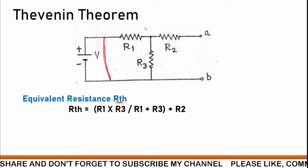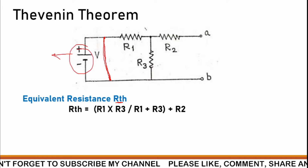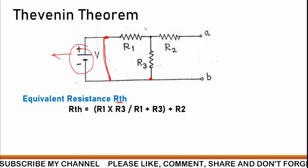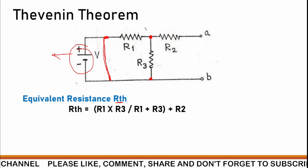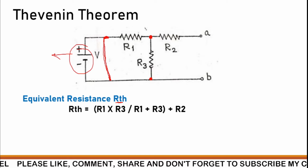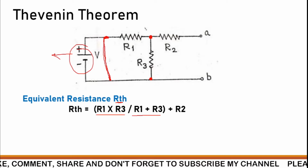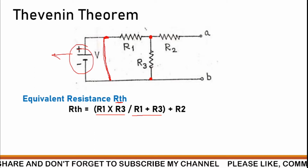So you can see here, if I short the source by removing the voltage source, the terminals of R1 and R3 get connected on one side, as well as on the other side. That means they are sharing the nodes, so we can say R1 and R3 are in parallel. For the parallel combination, R1 times R3 divided by R1 plus R3 is the formula for calculating the equivalent resistance.